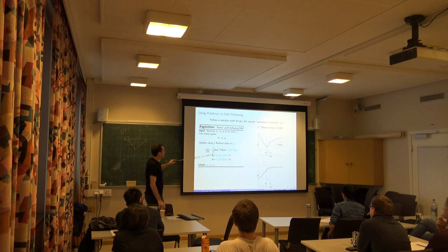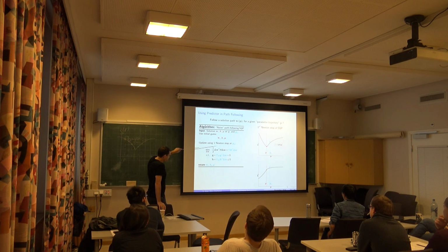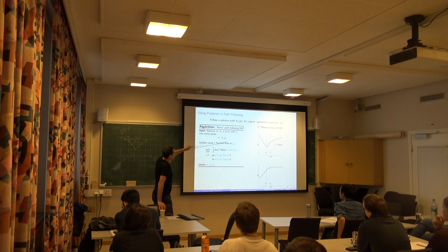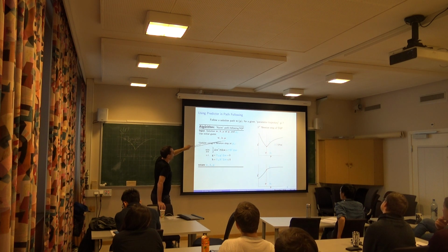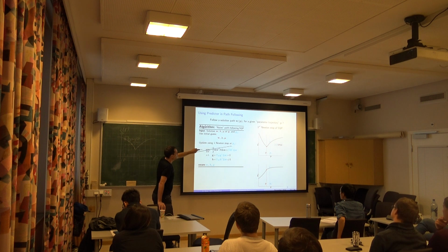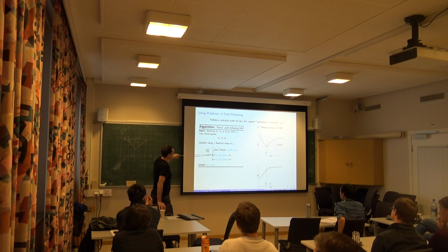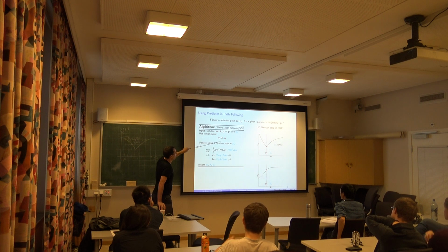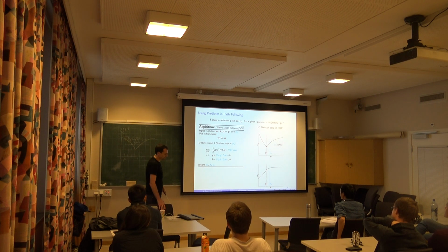And the reason here is that you're basically forming the next QP using P plus, but you still use an old initial guess. So you're right on the parameter when you form these matrices and vectors, so this GH and these gradients here, but you're a bit wrong on the initial guess.